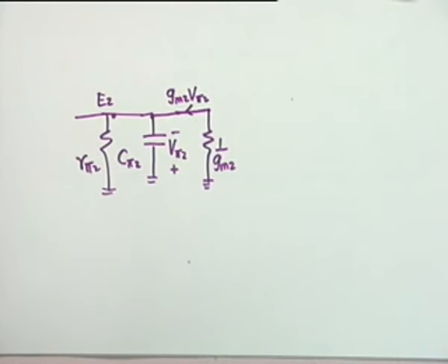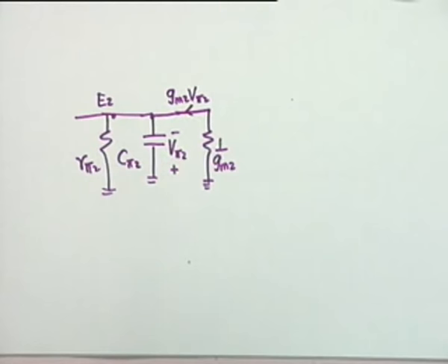And that's the trick. But the voltage 1 by Gm2 should be in series with the parallel combination of RL and C mu 2. Yes, sir. Well, it's not directly across the current, because it is not going to ground. Right, we'll come back to this.